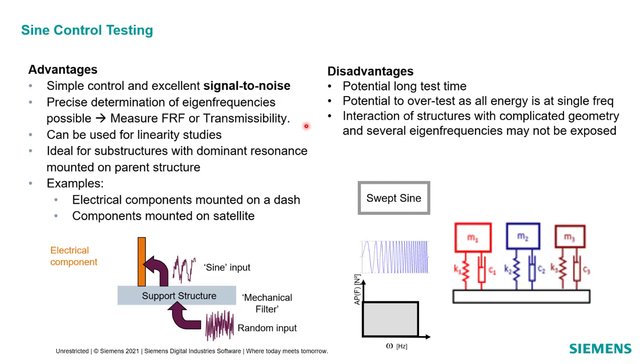If you're measuring just accelerations, you can use the phase information and that good signal to noise ratio to calculate good quality transmissibility functions, which have phase information. So we can use those for operating deflection shapes, calculating or even using as input to classical modal analysis, or using that for operational modal analysis also.